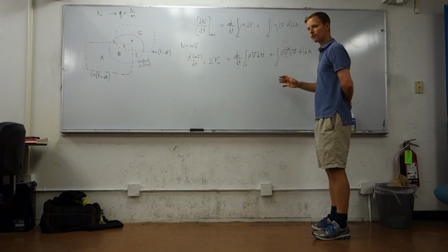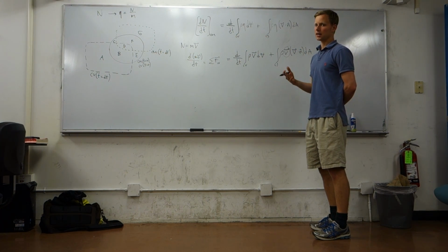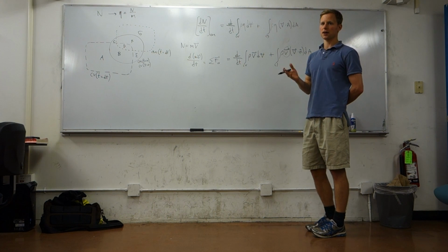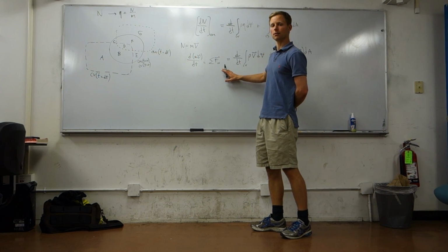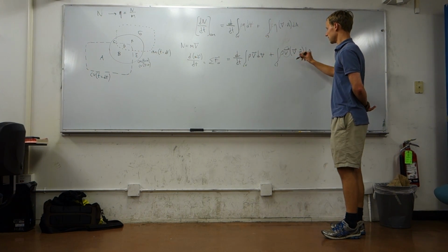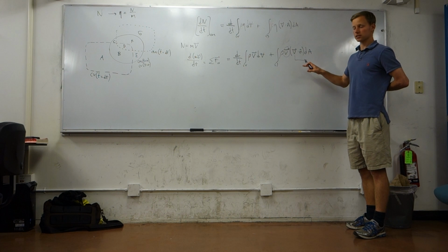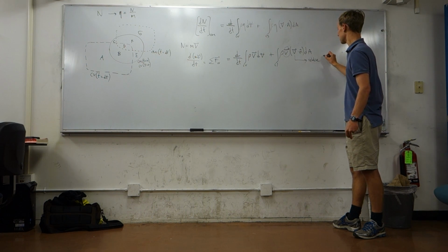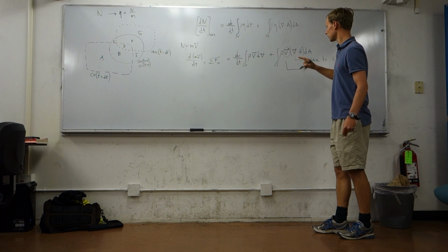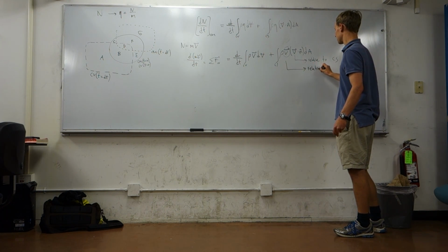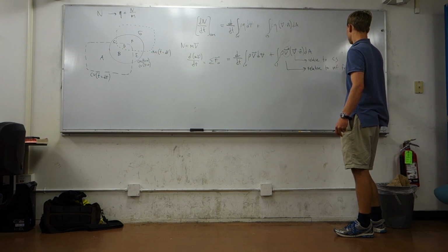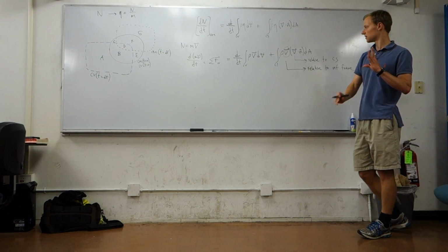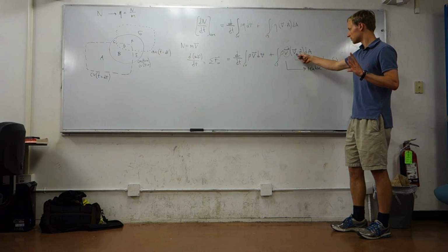This quantity here is the stuff we're balancing. If we're balancing velocity in a non-inertial reference frame, Newton's second law does not hold. We need to subtract out the mass times acceleration of the reference frame. This velocity here is always going to be relative to the control surface, because all that this is saying is the stuff that's crossing the control surface, relative to the control surface. This velocity is relative to our reference frame, which is not always the same thing as our control volume. If our control volume is accelerating and the reference frame is fixed, this velocity needs to be relative to that fixed reference frame, whereas this velocity needs to be relative to the control volume.